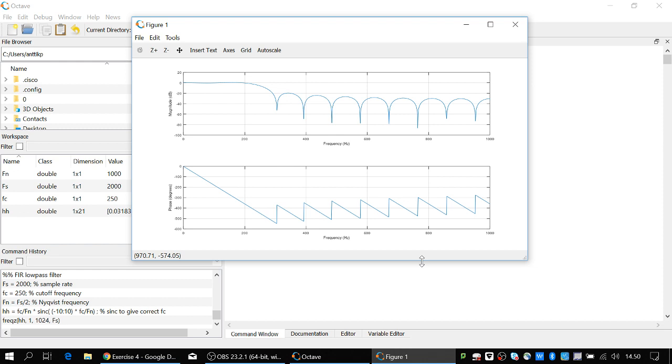So basically, this is a low-pass filter by itself, which has 250 Hertz cutoff rate, somewhere in here, -3 dB point, about 250. And the stop band attenuation, actually the stop band starts around 300 Hertz, but it's only about 20 dB. Not too much. Okay. But we got the cutoff frequency fixed.